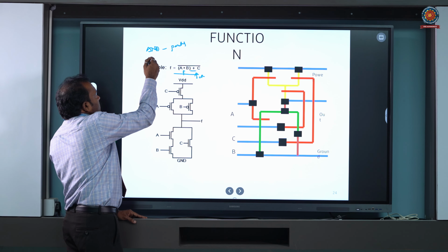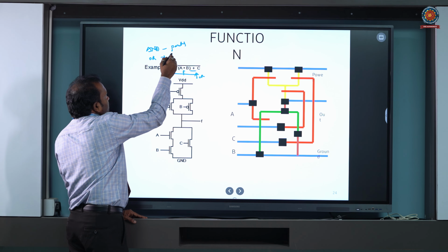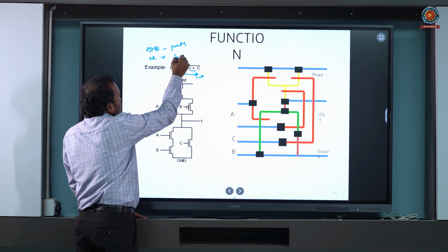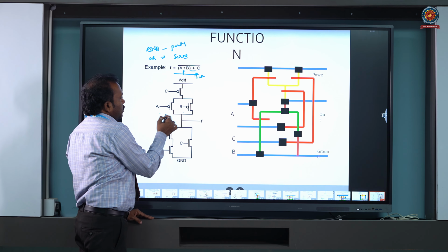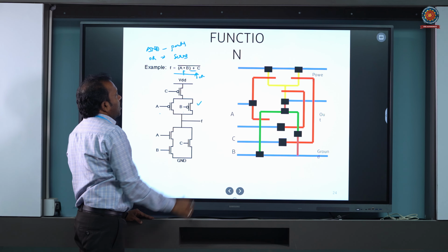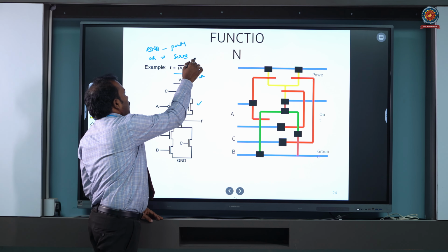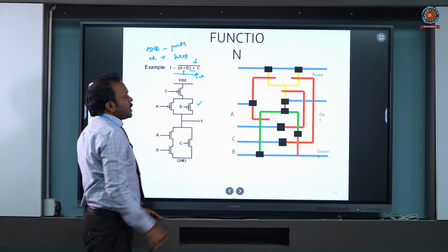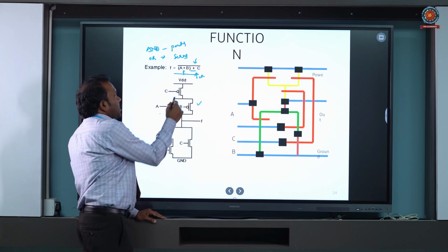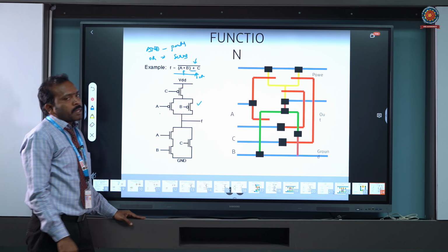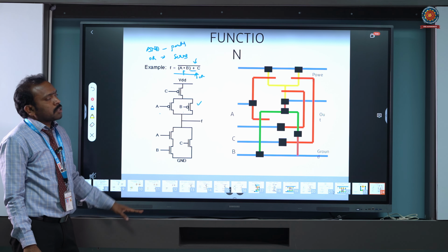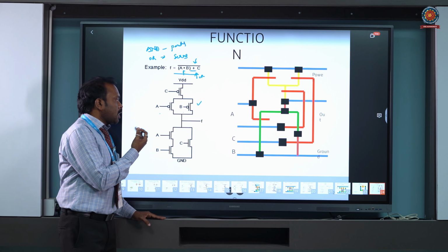And where the OR gate, the OR function is performed, they are in what? Series. Now as you see, A dot B, these two appear in parallel, whereas plus C is added in series with that, and this is added to the supply, and the complement that represents the output is an inverter, that we use CMOS technology to implement this function.